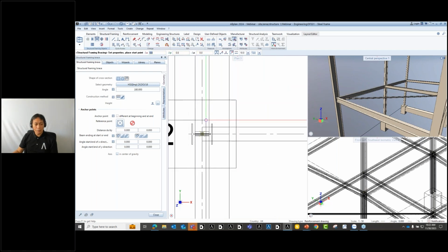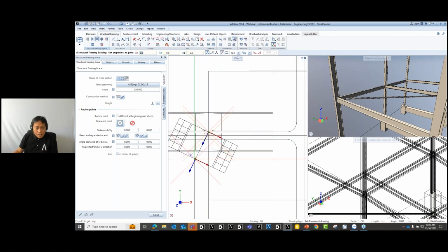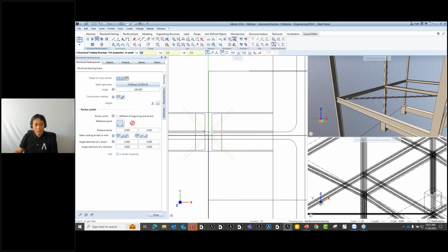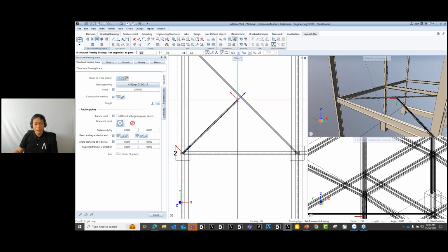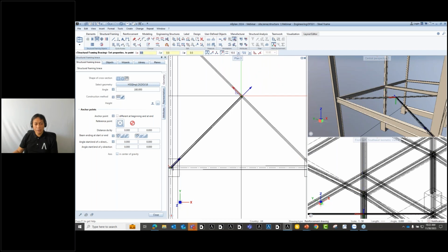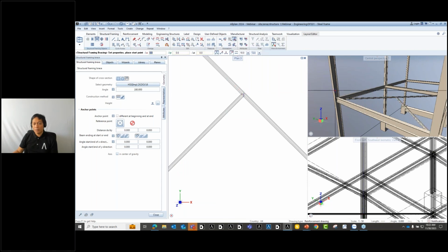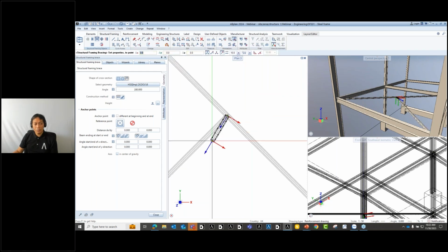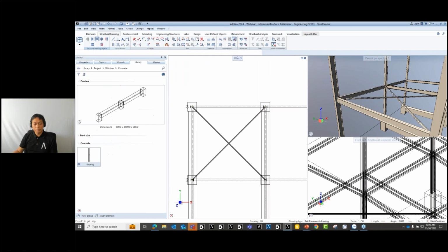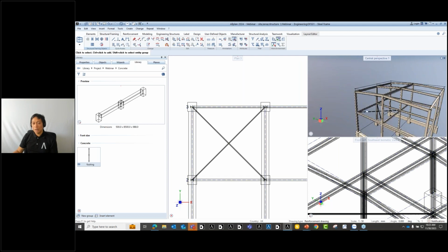Another thing is on this one, you have to provide, did I select the correct point? It has to be the correct point, so we should select this and then define it from here. You cannot go directly there because there should be a connection here. So I will just define 45-degree. I just cut it from there and then continue, click, and then click again. Okay. So for this case, I now have my bracing.